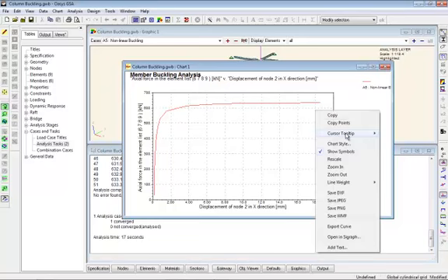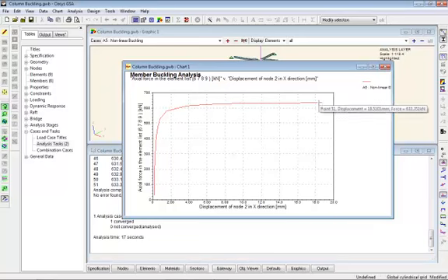And if I call up my coordinate points, we can see the modal buckling gave a capacity of 642, non-linear reached a limit at 633. So it's getting quite close to the modal linear buckling capacity, but it's saying much more than this, and the deflections will be large, very large.